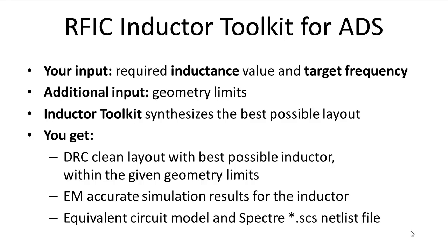So it has synthesized your inductor based on your electrical parameters, and you get the DRC-clean layout for this best possible inductor. You also get EM-accurate simulation results as S parameters, and you also get an equivalent circuit model, so a real physical model, and that's created also as a Spectre SCS file. So if you want to use this in Cadence, you can just take the DRC-clean layout and the SCS model to the Cadence world now.